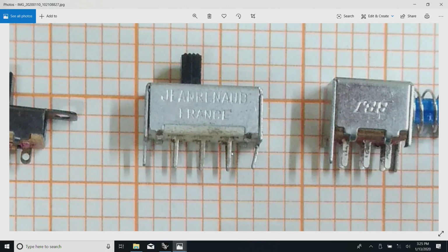The advantage of this is here you can use a printed wiring board, and the moment you have a printed wiring board, it is conventional not to stress the circuit when you operate this thing. Hence, 2 more mounting holes are given here. The advantage of these mounting holes is they ensure that once you solder all these things onto a printed wiring board, this is very firm and the stress does not come onto the connections here.